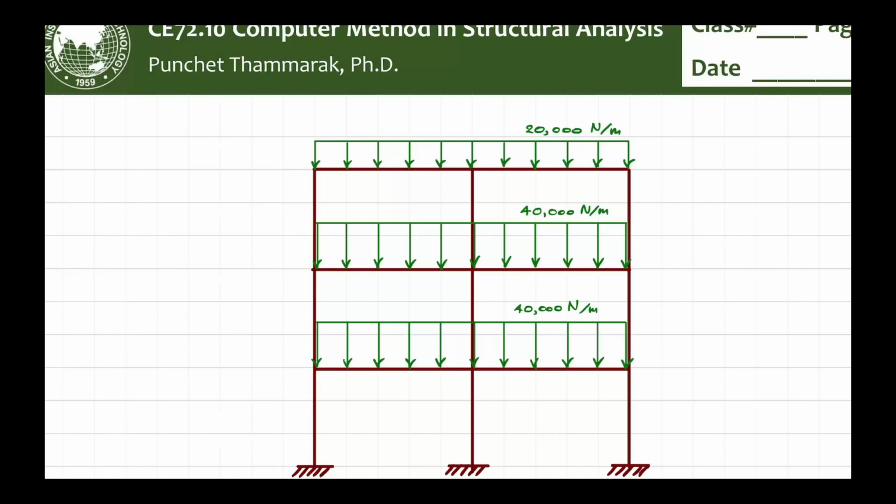Well, if you want, you can put some water blocking sealant on top, but make sure that roof sealants are not forever. They do not last like 30 years without maintenance. Generally roof sealant like this, in 4 or 5 years the system fails, you need to rip it off, and you can reapply the new coating, right?